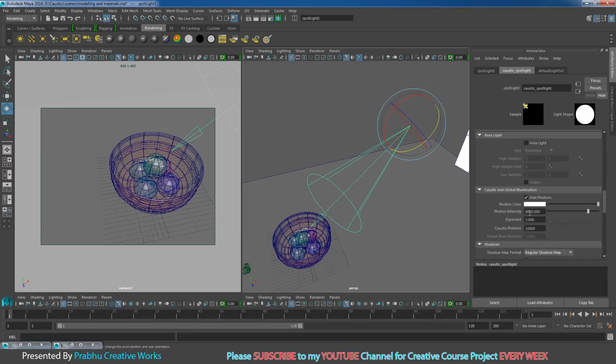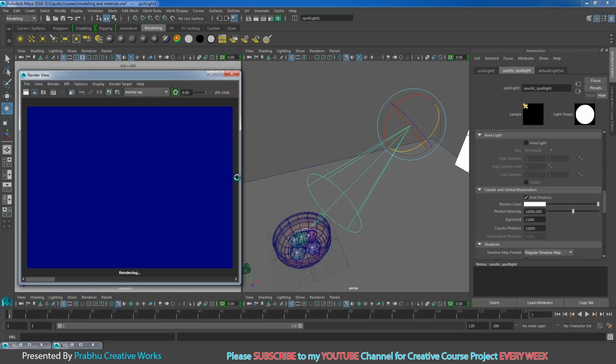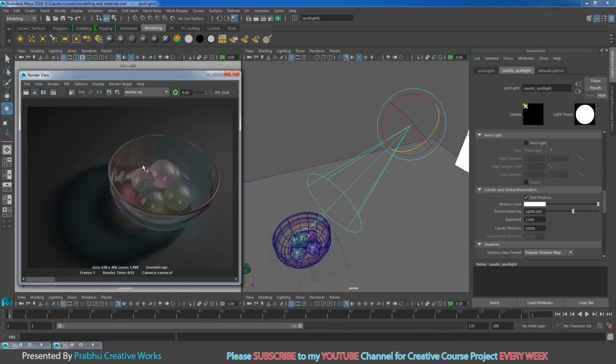Here we increase our intensity to 16,000. Now we want to check. So I will select this viewport and open render view again. I will click the keep image button and then click render again. Now check, see here our caustic light has increased.